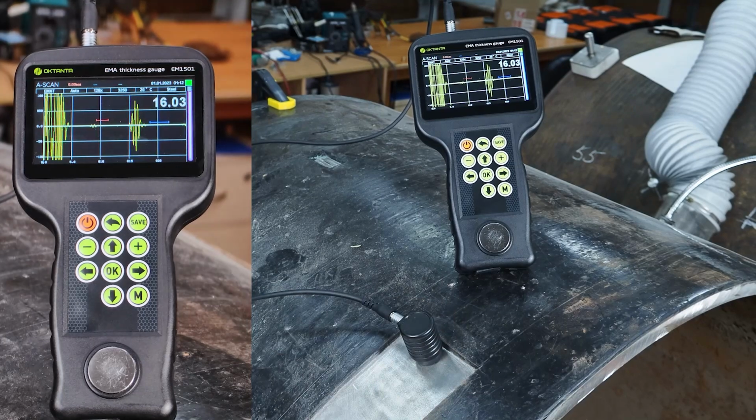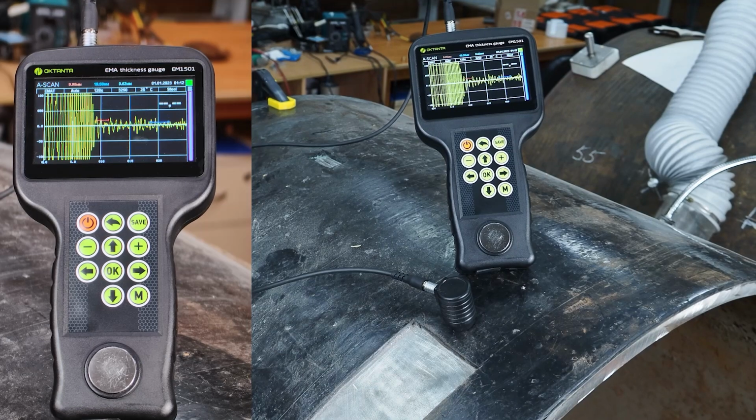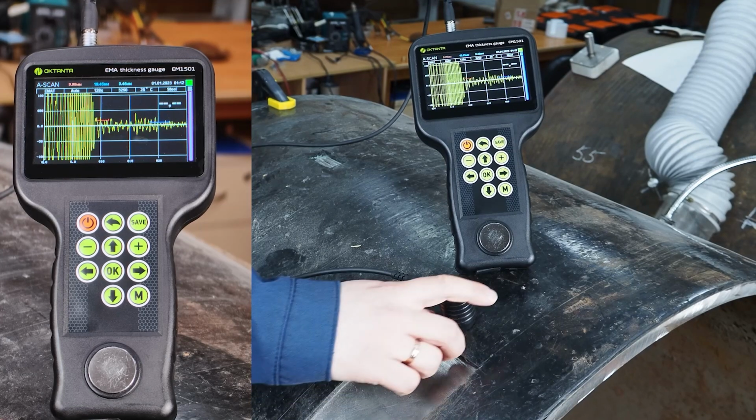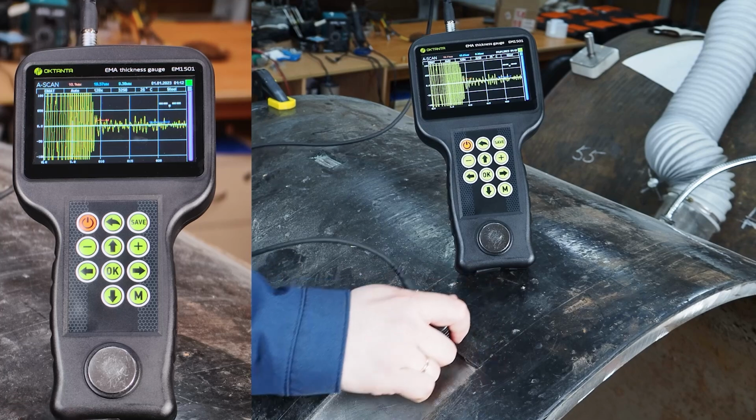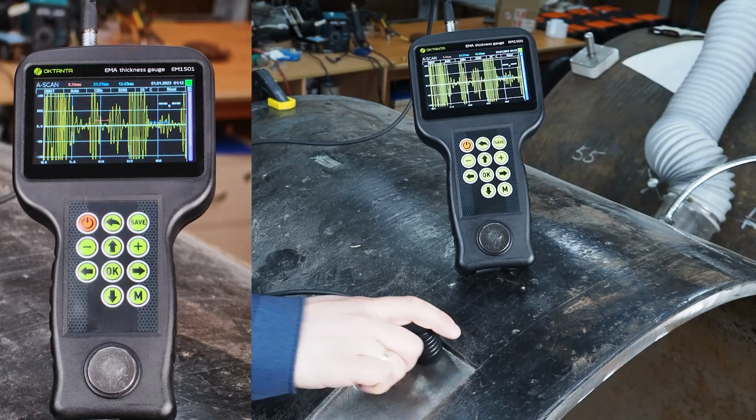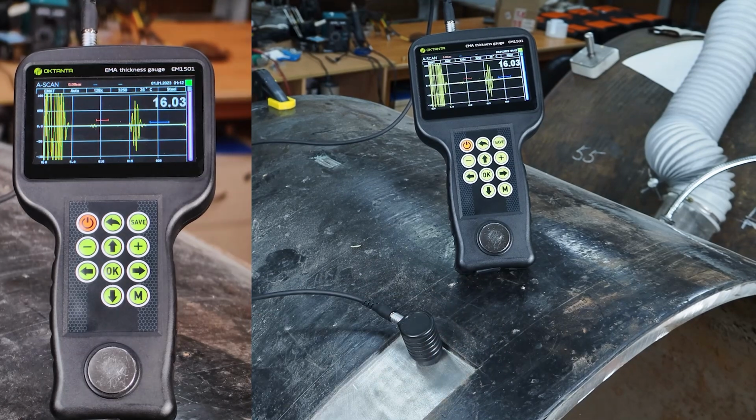As soon as we bring the transducer to the test object at a distance sufficient to form and receive an acoustic wave, bottom signals appear on the A-scan, by which the device begins to measure the thickness. Accordingly, when operating with the device on complex test objects, it is necessary to monitor the level of bottom signals on the A-scan.